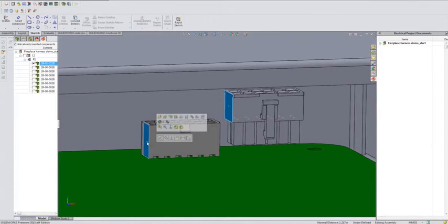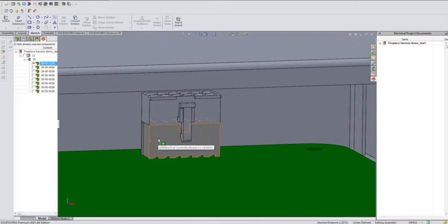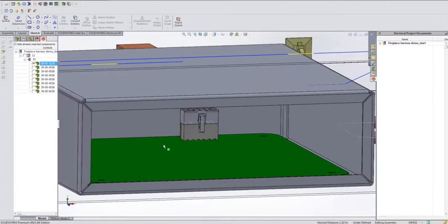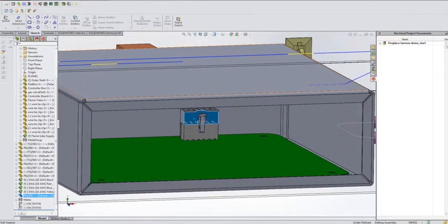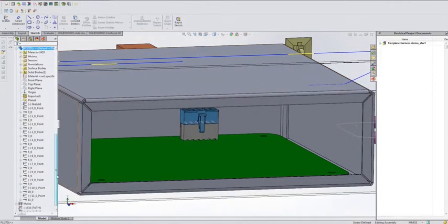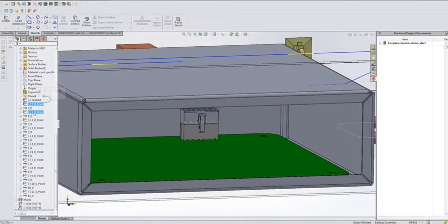So nothing too new. On the mechanical side, it's leveraging what already is still existing. It's going to use a routing engine to route up all the wires here. In addition, you'll also notice that I don't have to worry too much about the connection points because this component already has it. So of course, as you're designing, there'll be cases where you can use existing geometry, but if not, then you can always create your own using our electrical component wizard inside the SOLIDWORKS Electrical. It'll then walk you through adding in whatever you need, like your connection point, your route points, and any kind of things like mate references.